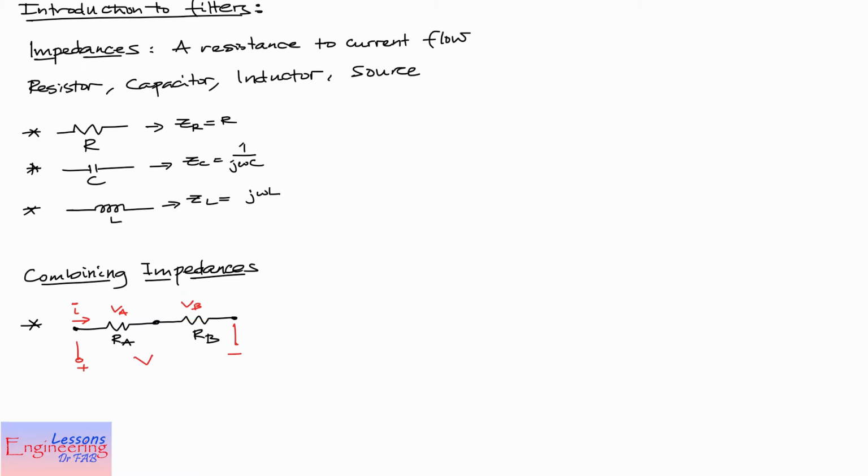Alright. Now we can start with calculating the total resistance. We know that the voltage across is V, and our total can be given by the voltage divided by the current, and that should ideally be the sum of the two resistors RA and RB. From this it follows that V equals I times (RA plus RB). The current that flows through the whole circuit is constant through that branch. It's a continuous branch, so we expect that current to be the same throughout RA and RB.